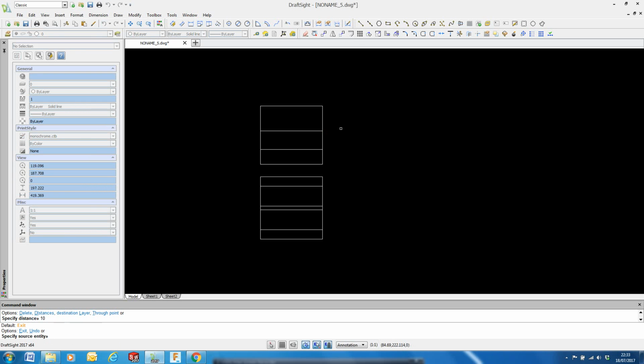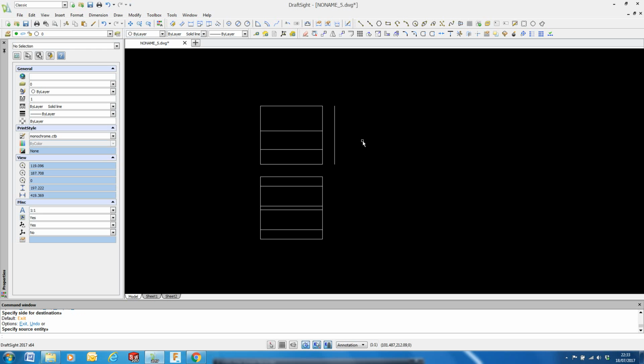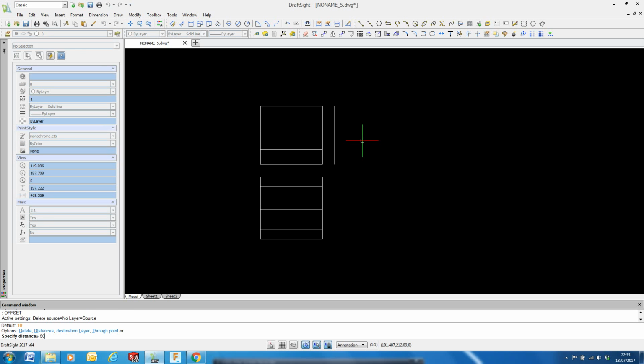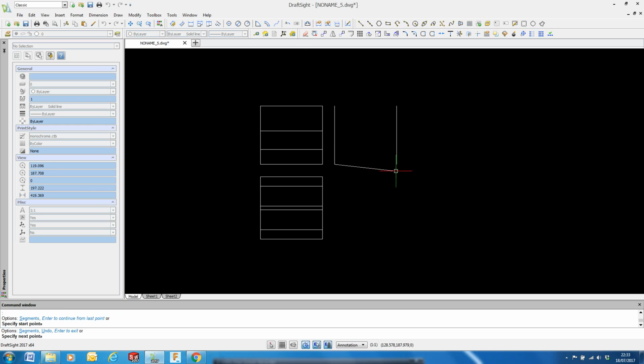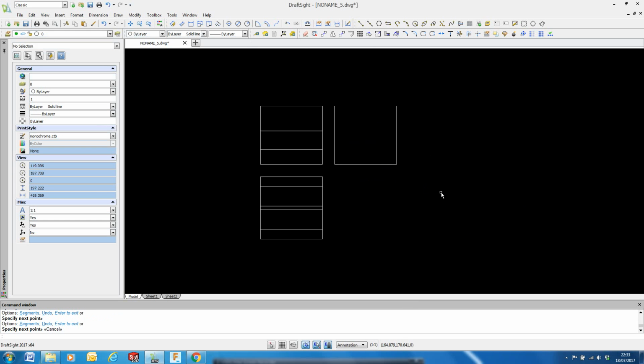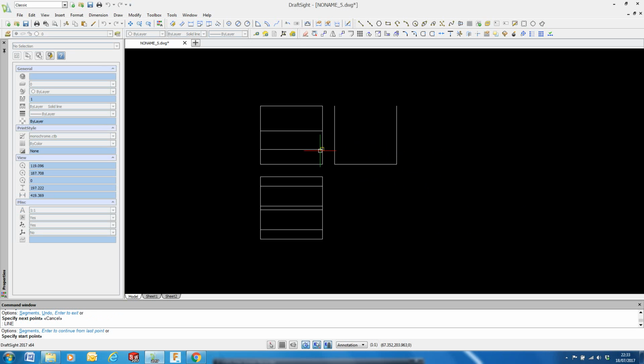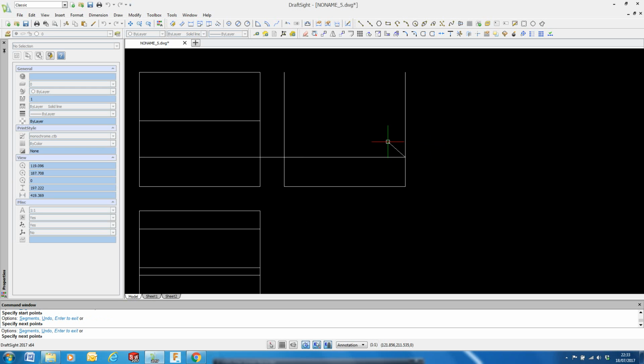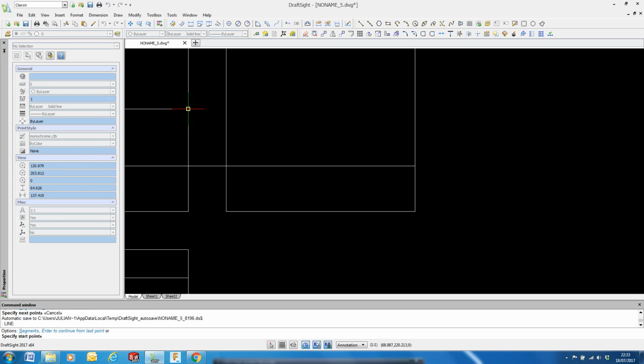So let's take an offset, 10 millimeters. That's what we said we would do. That's the start. It is 50 millimeters wide, so we can return, 50 and make that 150. I can use a bit of the line tool. I'm going to return to restart the line tool, and I could use E tracking, possibly link up there, but I'm just going to draw from that point to perpendicular. Let's zoom in a little bit.